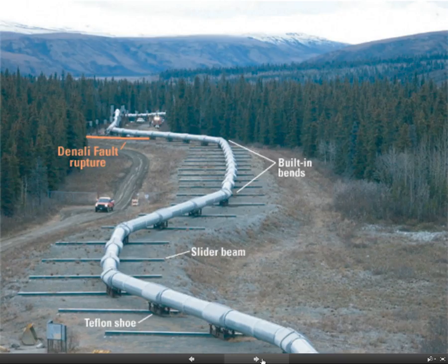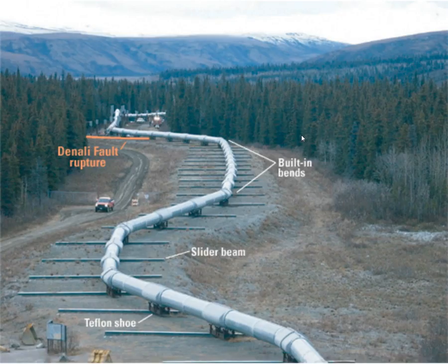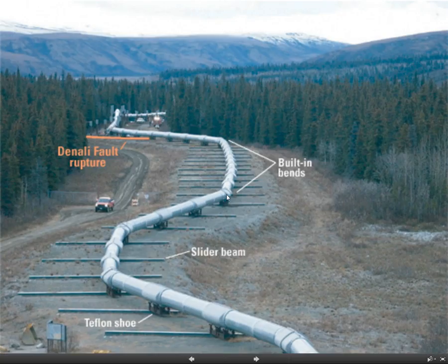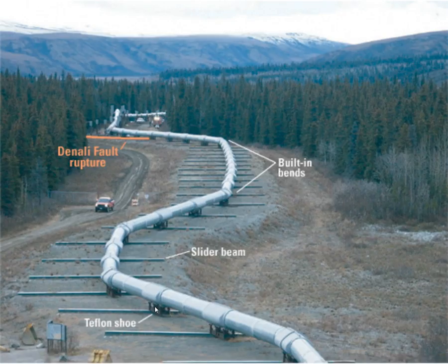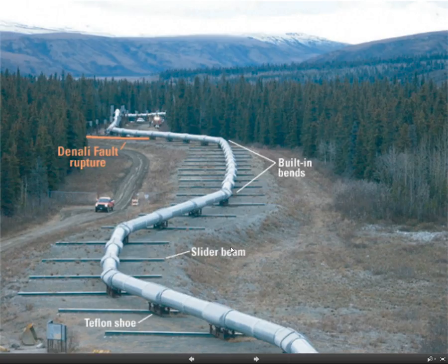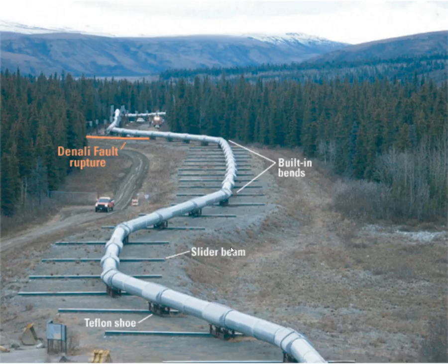And the pipeline here, I thought this one was really interesting. There's a fault here, so you've got to remember the Earth doesn't always stay completely still either. And so that means the ground here may be slowly moving, or maybe even be prone to small earthquakes and things like that. So this pipeline has some bends in it, and it looks like they've got, they're called here Teflon shoes. So Teflon is quite slippery or can be used to reduce friction, so that the pipe can actually slide slightly, so that essentially if the ground moves, the pipe doesn't just crack, but the pipe can move a little bit with it.